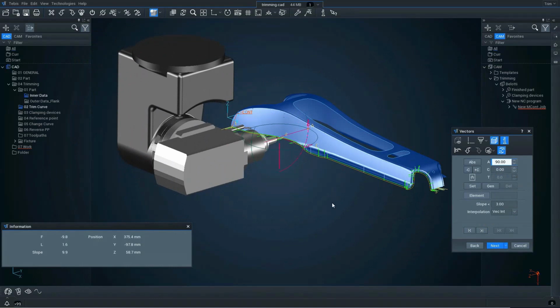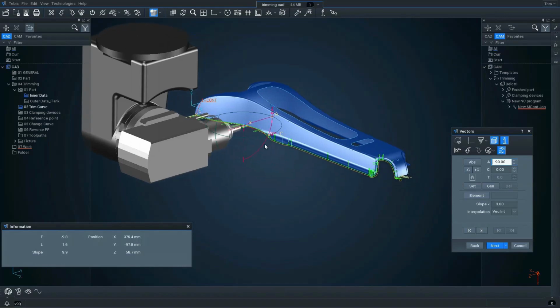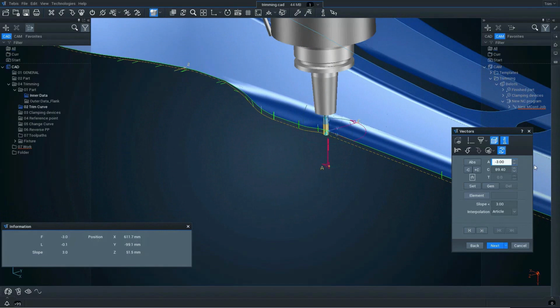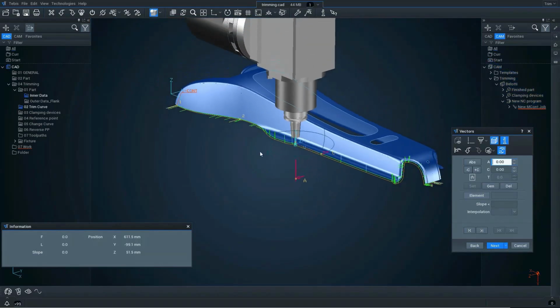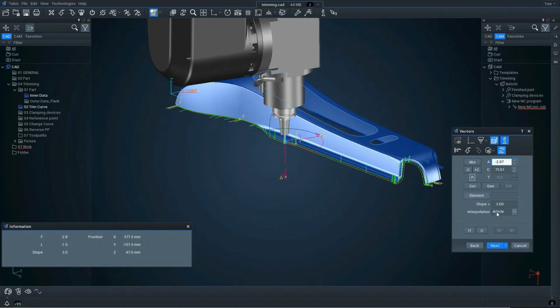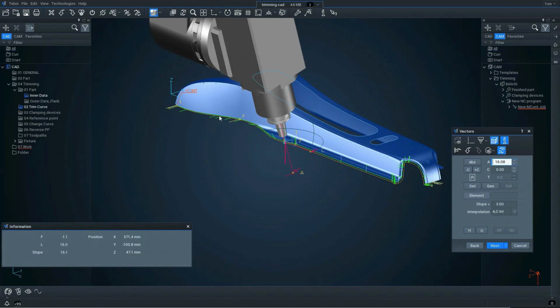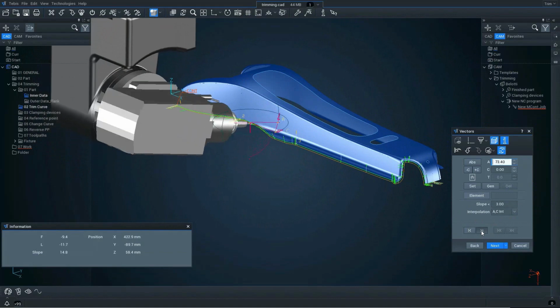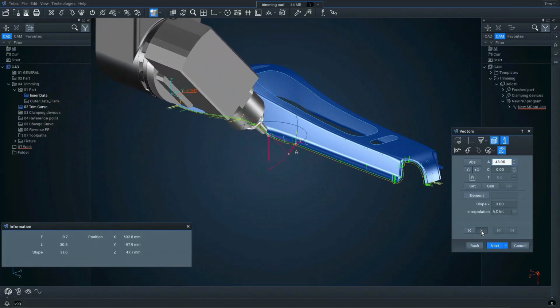What we'll do is continue to break the curve down into large chunks like this and use these controls to get the best possible toolpath we can. So if we come to this area here, and again, I'm going to nominalize these values and create a set point. So now we have the head vertical. We're then going to tell this to rotationally align. So what we have now is a toolpath that goes from dead horizontal and rotates smoothly and cleanly towards point 3.